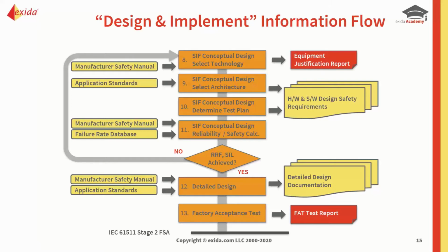So the test plans. Then the conceptual design itself, by selecting the sensors, the logic solver, the final elements, and then doing the SIL verification. Do we achieve our risk reduction? If it's a low demand application, does our PFD average meet the target and the risk reduction that we need, the RRF?